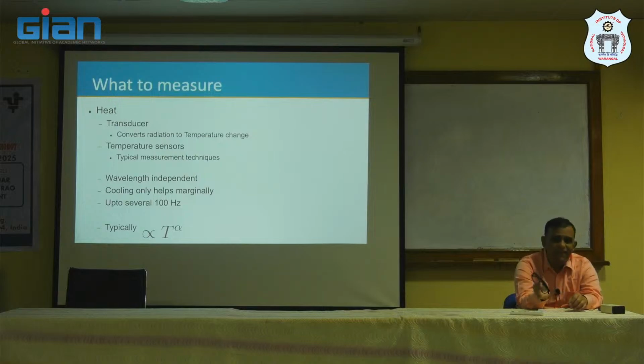However, for heat based sensors, that does not do much good. Cooling does not help. Cooling helps with sensors measuring infrared radiation. The other drawback of heat based sensors is that they are not very good in the frequency domain. They can only measure up to 100 hertz.